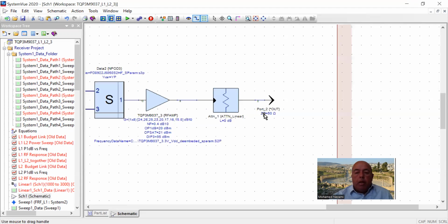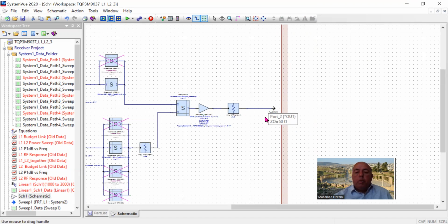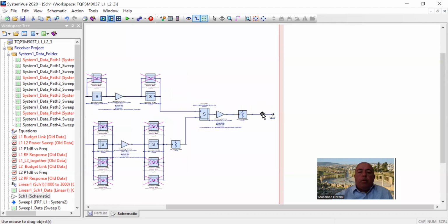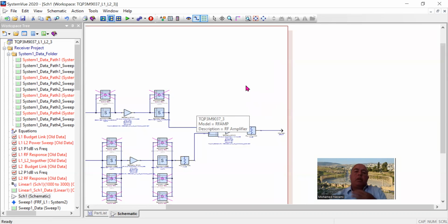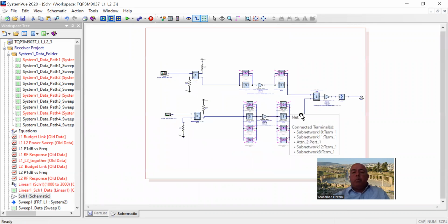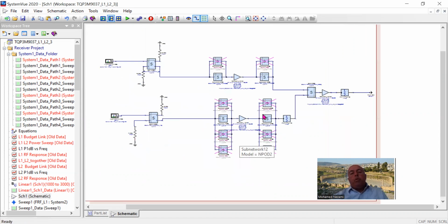We have the DC power regulation. The DC power comes in through the coaxial output cable, similar to SATCOM LNBs, where the DC comes from the RF output signal. We have a duplexer that blocks the DC from going back, and then you get it locally here. You have to regulate it, and you have to include some ESD protection on these active devices and on the input of the antennas. So you could build the whole system in ADS and then go to the layout.